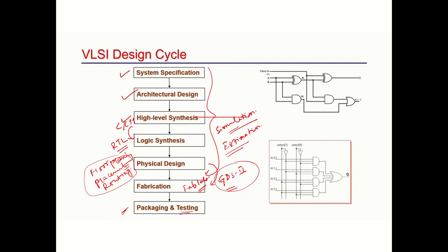So exactly here you can check one example of a circuit. What is this particular circuit? As it is very small, I think you will understand that it is an XOR gate, another XOR gate, AND gate, AND gate, and then we OR this one. So XOR and AND give us the half adder, and this is another half adder. So this performs as a full adder circuit.